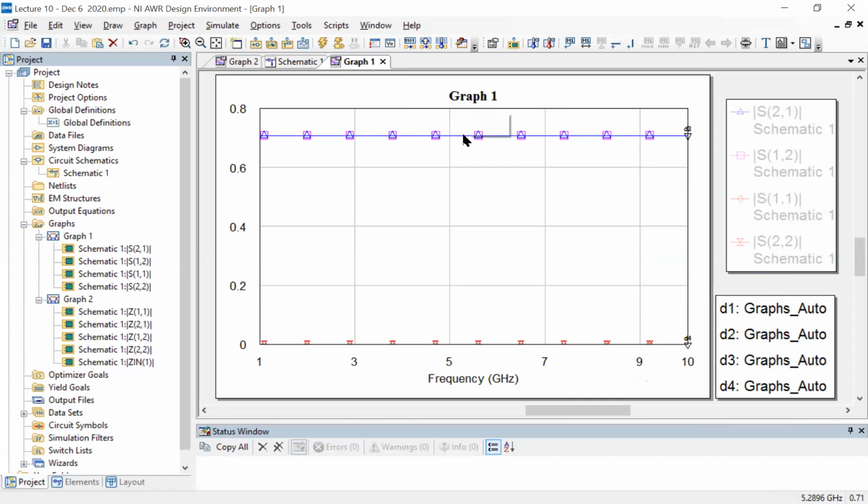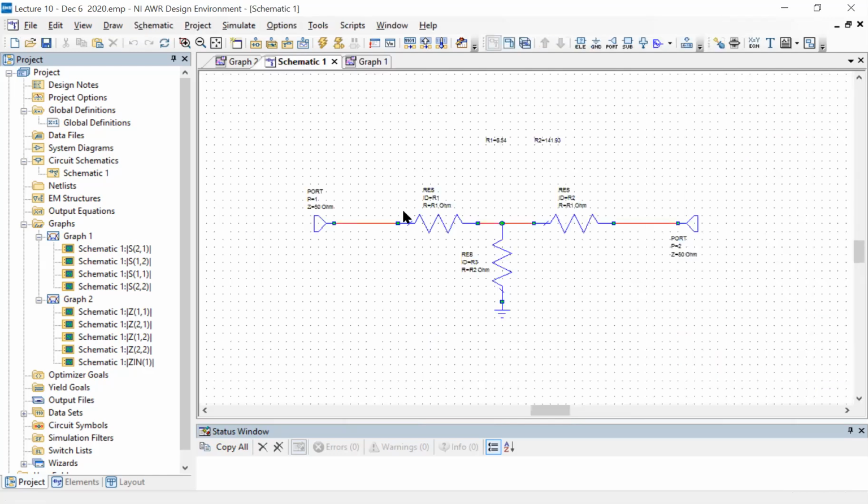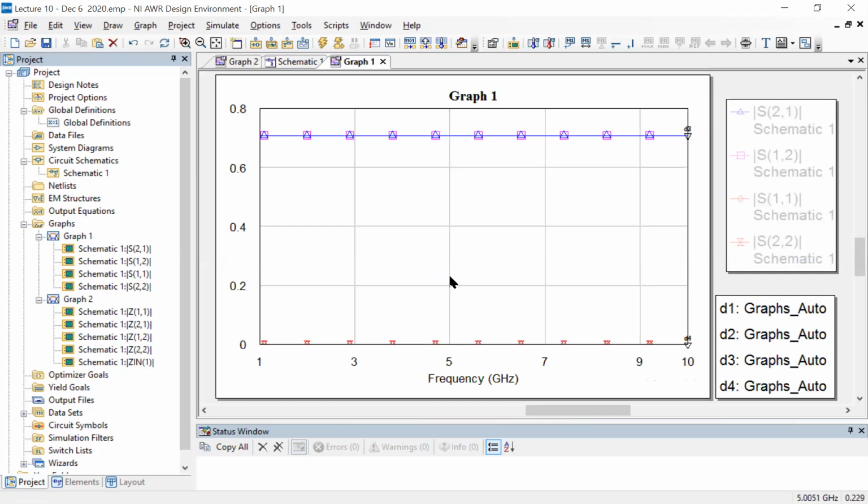The square of that is 0.5, and that's a half. So you have the situation where the signal is attenuated by a factor of 2, going from one side to the other side. It's perfectly symmetric and reciprocal, and of course not lossless. And that's basically what describes this 3 dB attenuator.